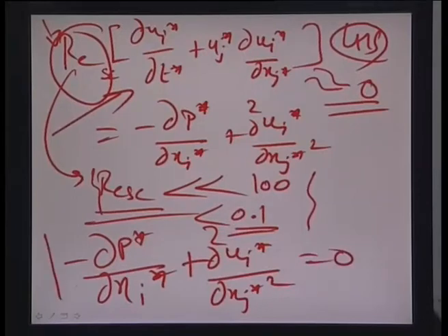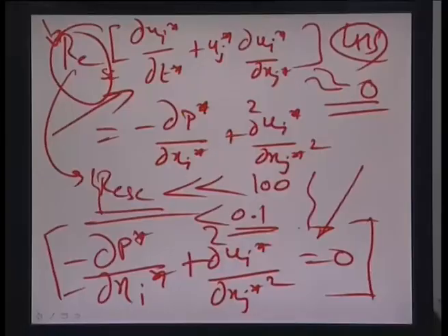is equal to 0. So this is a very important result that we have established here: if you scale down the conservation of momentum equation at the scale of the Reynolds number being very small, or micro scale, you immediately find that the equation becomes time independent, and therefore there are certain effects and situations in the micro scale which become very prominent where time no longer matters, things like mixing.